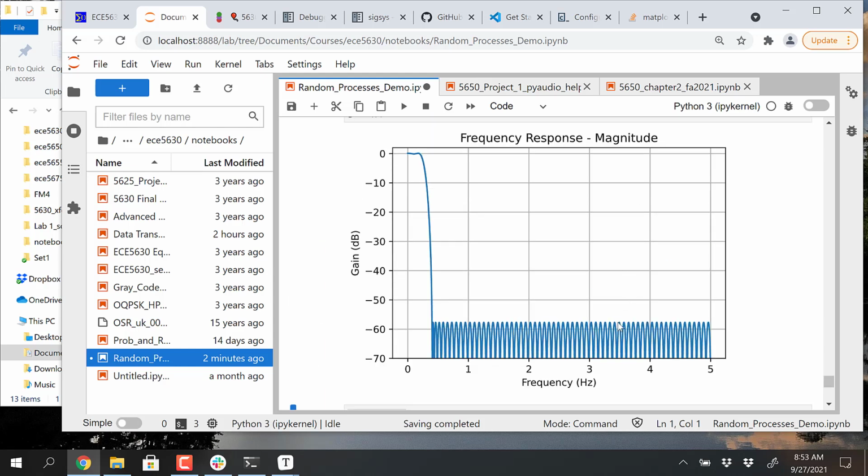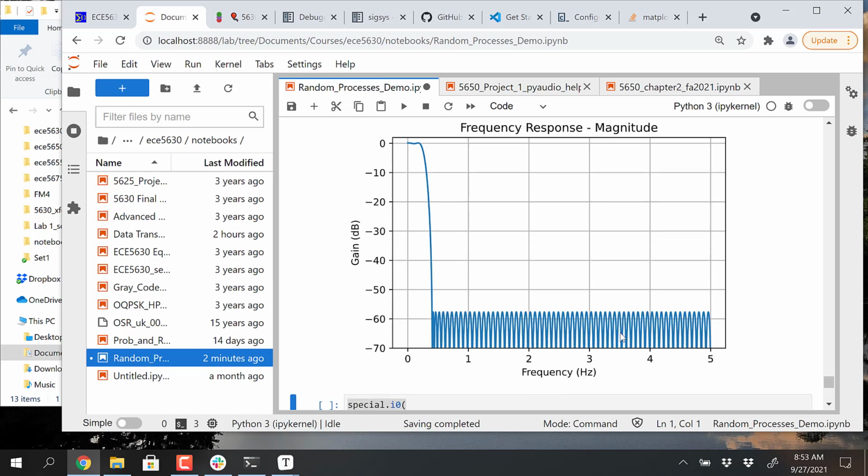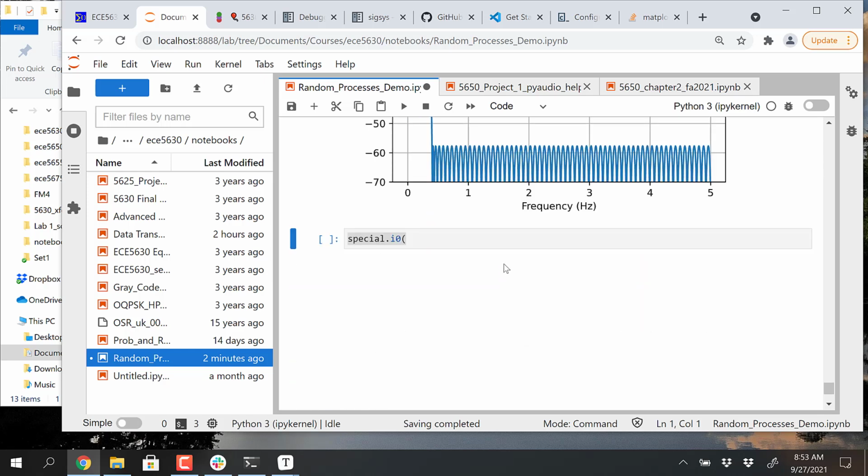If I want to model this within DSP, I can make this look like a bandpass process. Where do I want to put the carrier? I'd like to have it well above this action up here, but where do you think it should go? Should it go right in here at 3.5? I mean, I can certainly do that. Or 4? I'll just do it at 3.5.